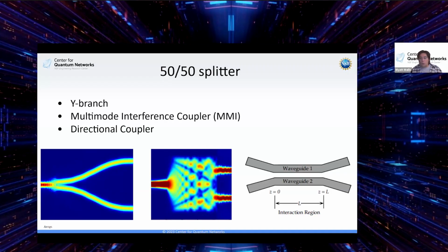The next one after that is the multi-mode interference coupler, or an MMI. What this uses is one waveguide coming in, and then it connects to a larger rectangular region, which is kind of like a free propagation region. And then at very specific heights at the other end, you have two waveguides coming out. It all works with the same boundary conditions and the same math. But because that rectangular region is so wide, there will be certain solutions on the other end where your two waveguides need to be, to where it'll actually couple into those two waveguides at the wavelength you want.